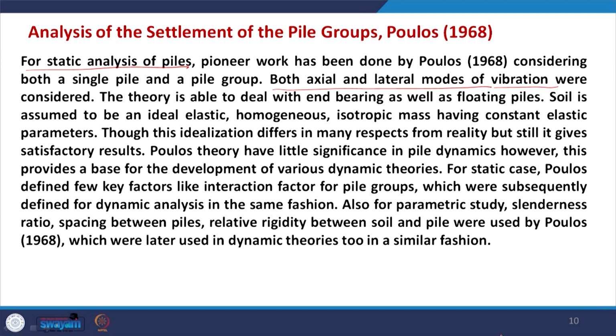That means the vertical mode of vibration is considered as well as the horizontal mode, and the theory is able to deal with end bearing as well as floating piles. So, that means it is very versatile.